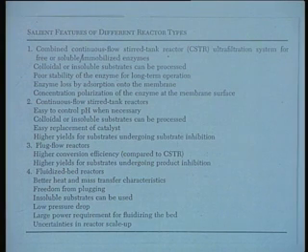Then the other category of enzyme reactors, fluidized bed reactors, as I mentioned earlier, are much better suited for heat and mass transfer characteristics, and freedom from plugging. Very often if colloidal substrates are to be used, a plug flow reactor faces problems in terms of plugging or choking of the column. In a fluidized bed reactor, insoluble substrates can easily be used.